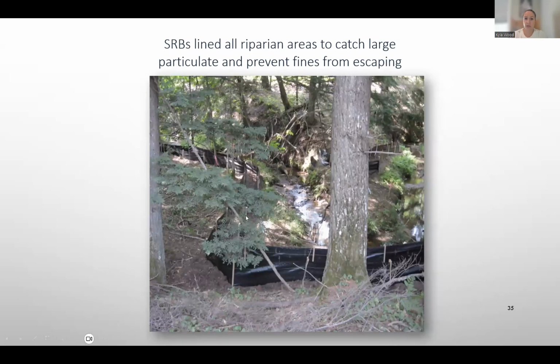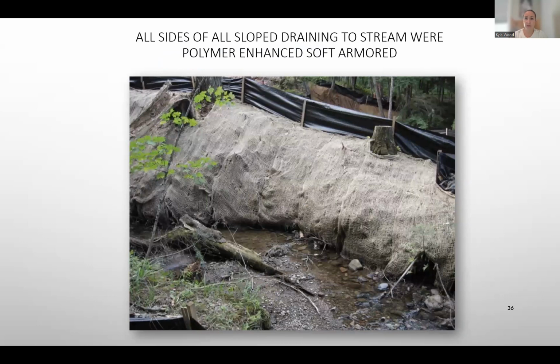Here again are some more examples, just rows and rows of these sediment retention barriers that we used as that final line of defense before the stream. We also soft armored the slopes that led down to the stream to collect some of the particulate.